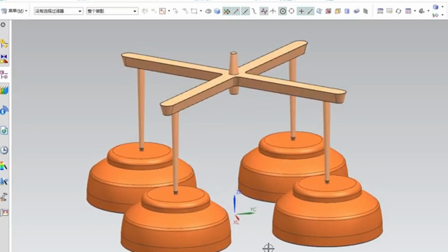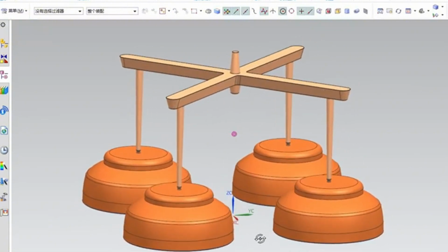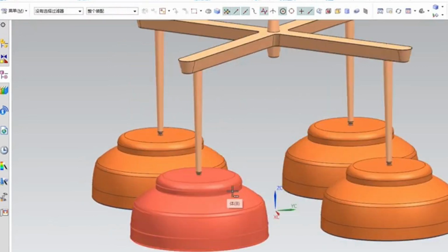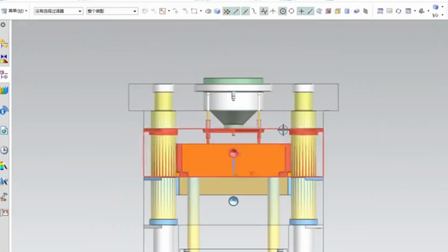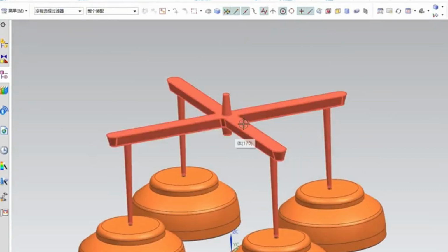Gate design. The location and form of the gate are critical to the quality of transparent products. For transparent products, hot runner gating systems are a better choice, because they allow the plastic melt to fill the mold cavity evenly and reduce fusion marks. For example, pinpoint gating enables the plastic melt to enter the cavity uniformly with less pressure and speed, which is conducive to the reduction of flow marks and bubbles, and makes the product appearance more transparent and polished.